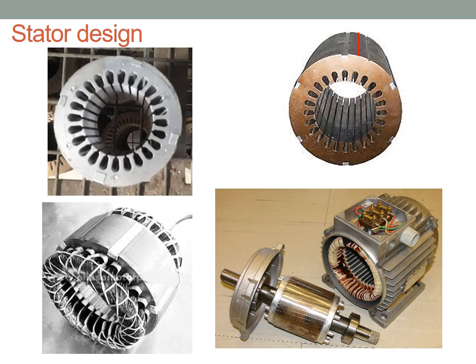So you can see here, in this stamping there are a number of stator slots, along with the teeth. There are a number of stator slots embedded over the periphery of the stampings. These are the slots where the winding is embedded, and along with that, the stator tooth comes. Now you can see in this picture, the winding is embedded in the slot.